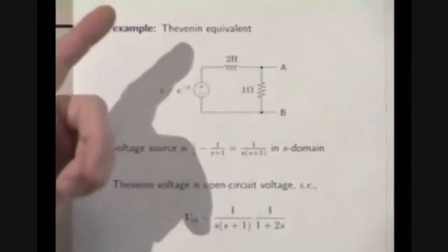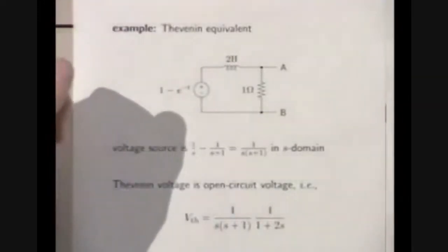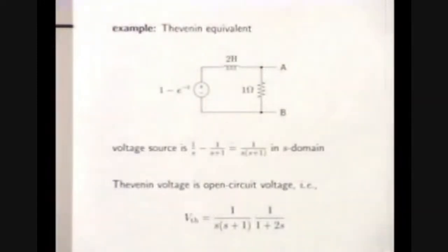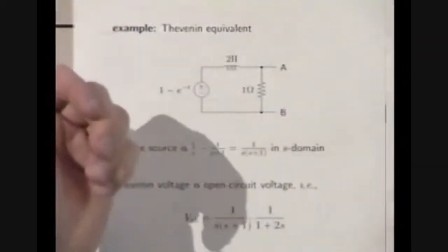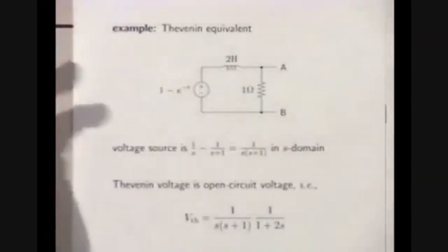When you write Z1 over Z1 plus Z2 and divide, right, division in Laplace transforms is sort of like multiplying by the inverse. You're actually solving a differential equation when you divide. After a while, you don't care, doesn't mean anything to you, and you just say it's 1 over 1 plus 2s. You don't even think about it. But you are, in fact, solving a differential equation.